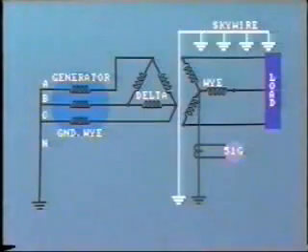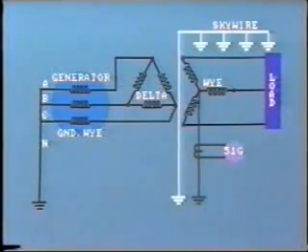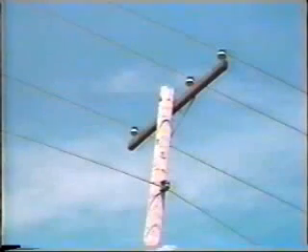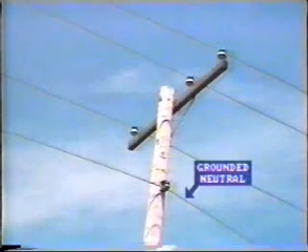For example, with high voltage transmission lines, the steel towers are connected together at the top by a bare ground wire or sky wire. This ground wire goes right back to the substation structure, which is, of course, grounded to the mat. Consequently, the ground wire provides a parallel path to current flow through the earth. Similarly, on four-wire distribution systems, the neutral fourth wire is usually grounded. And this, of course, provides an excellent path for ground fault current flow.